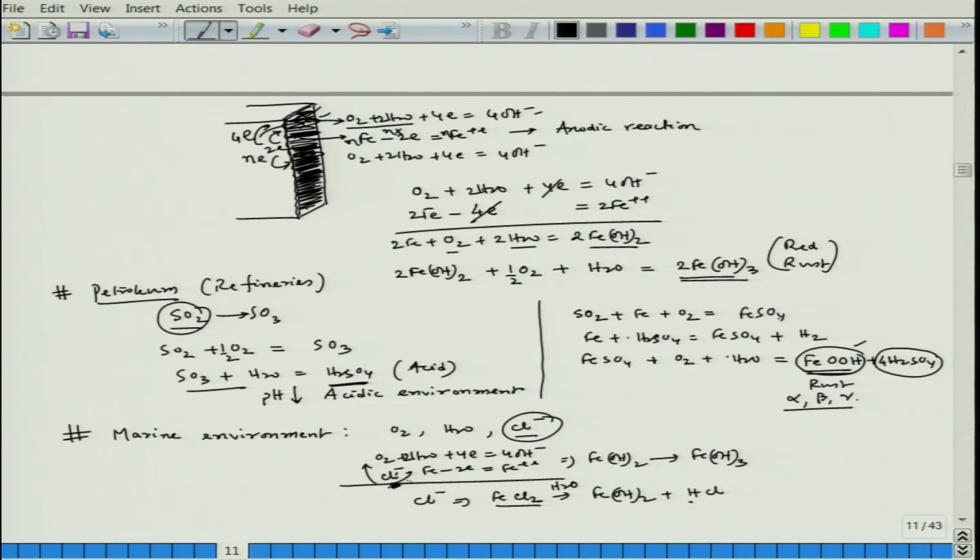So, this HCl would form here, and because of the formation of HCl, the acidity increases and the pH drops in this location. Actually, the pH to start with is close to 7, since this is a neutral solution. Now, at that particular corrosion point, the pH can go down to 2 to 3. So, that means it becomes highly acidic, and the corrosion happens here.